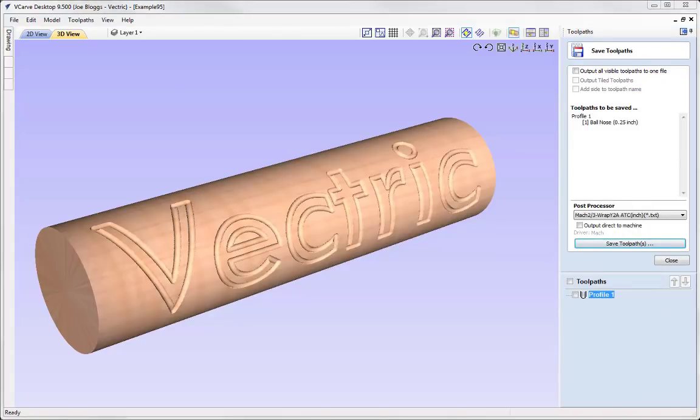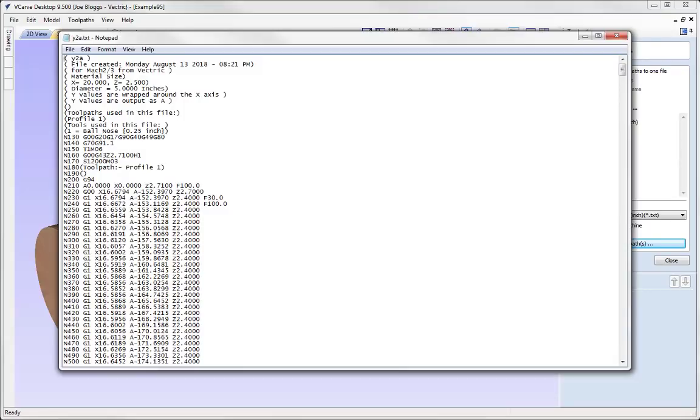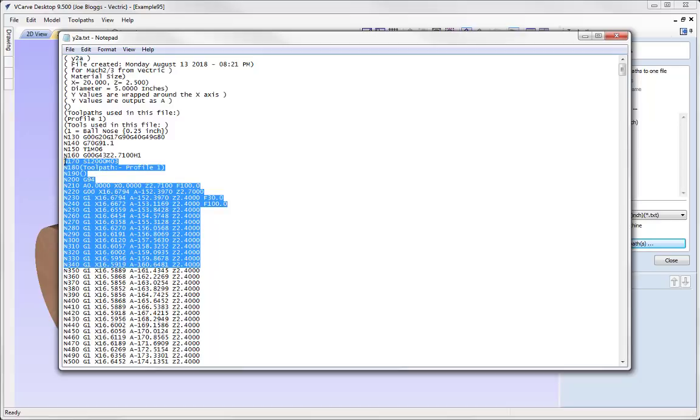And then I'm going to pop open that text file now, and we can see at the top it's specified the length. We've also got the radius and of course the diameter there. So you can see that those values have all been entered into the top of the header for the G-code file automatically, rather than the manual entry of V9. So for VCarve Desktop users, it's a much simpler process than what people have been used to with VCarve Pro and Aspire in the past.